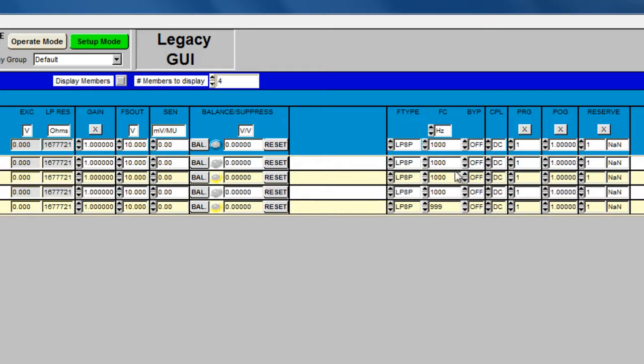The programmable filters can also be bypassed out of the amplifier circuit. This allows the programmable filter to be removed from the amplifier circuit, allowing the channel to function as a wideband amplifier only. Each channel's filter can be independently controlled to be bypassed or in the circuit, and this is set by the bypass control switch for each channel.